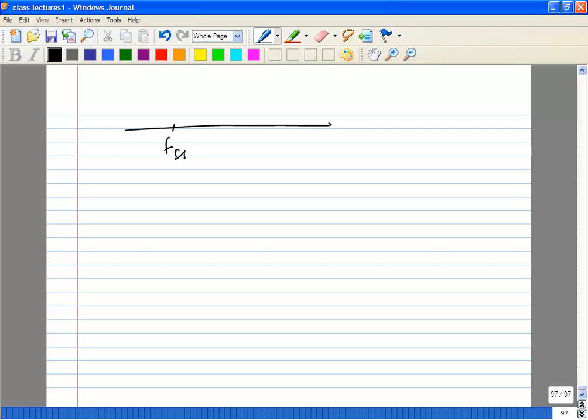So at FIF equals 545, you're going to get your desired signal. And from 1620 you're going to get something, but it's going to be much smaller. That is your image. And at 535 kilohertz you're going to get your 1610, right? Your channel at 1610 is going to come to 535, but you're going to end up putting a filter on top of this. Let's use a different color. That is your IF filter.